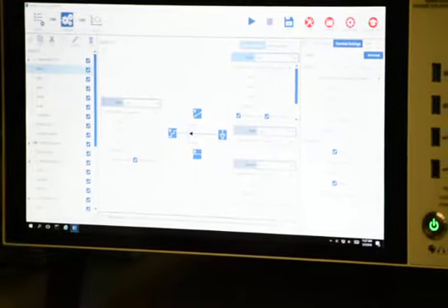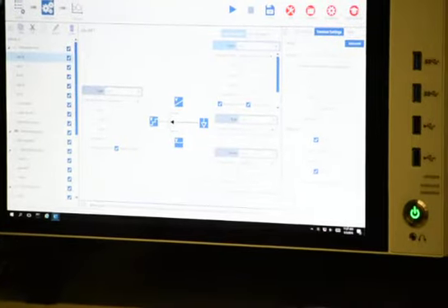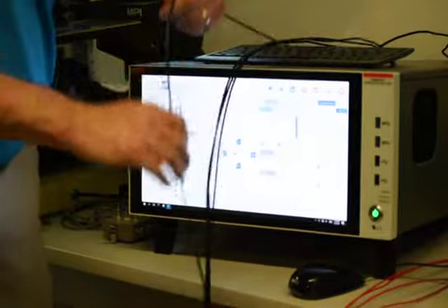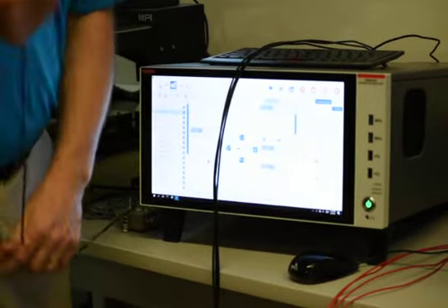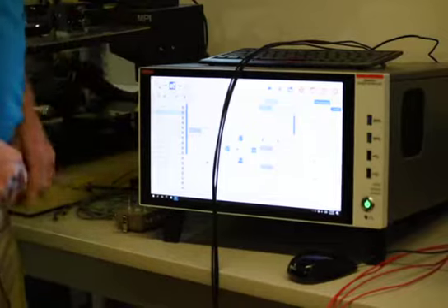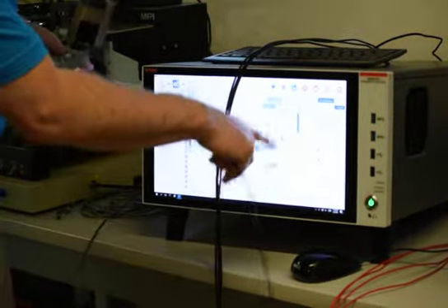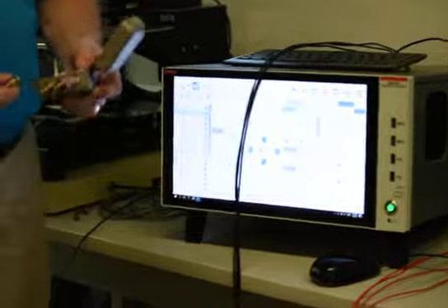Okay, so we got SMU tied to the source. So we're going to take this guy, SMU1, and find the cable for it. Do you think you will have time so that we can do some measurements on my device, if that's okay, for that voltage range? Sure. What I'm going to do is follow the definition that's on here. It says SMU1 is my source, which matches here. SMU1 is my source. SMU2 is my drain.